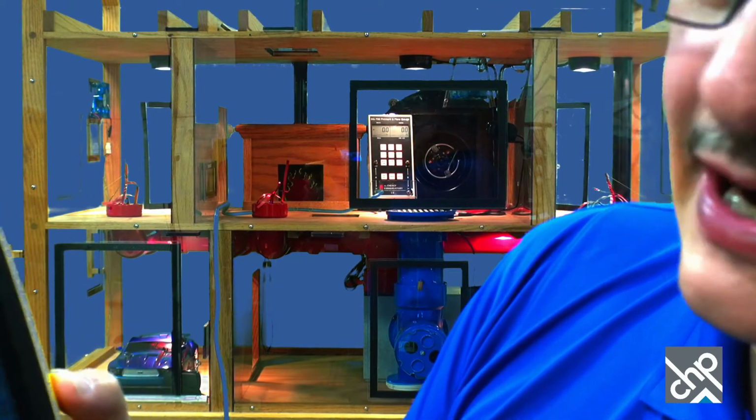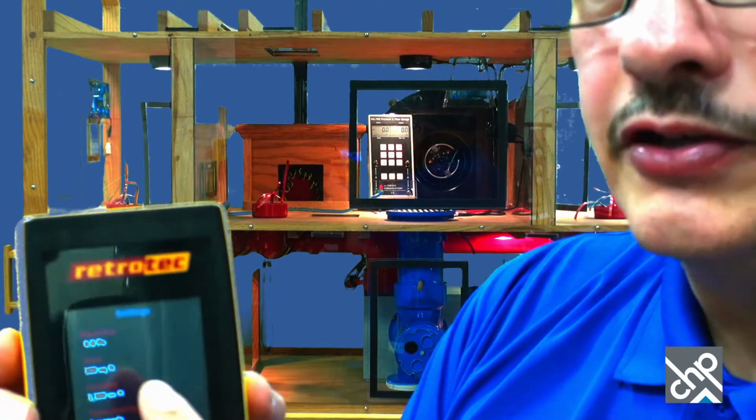And then the baseline, it actually shows right there. So what that does is, if there's pressure on the building from wind or stack effect, before you even do your test, you might be at a minus. In this case, it was actually a positive 0.8, but I was just moving the manometer around. But there might be a pressure between the building and the outdoors. And when you do that baseline, it basically neutralizes that.